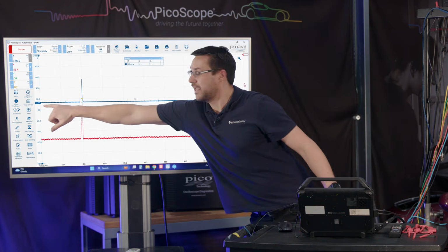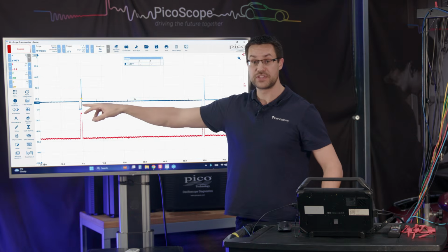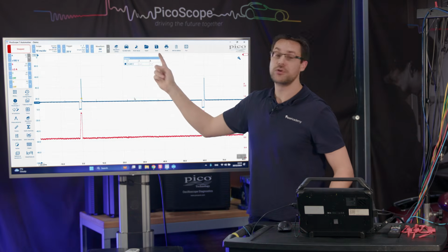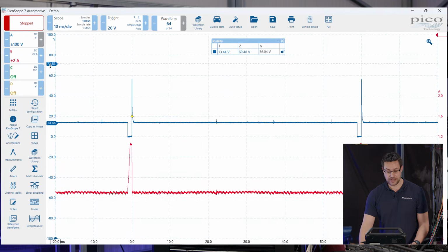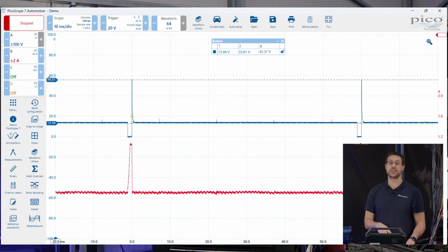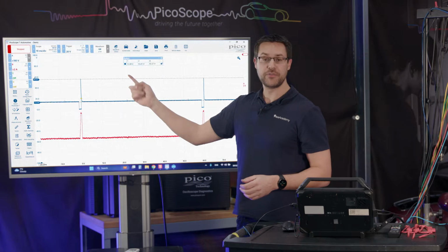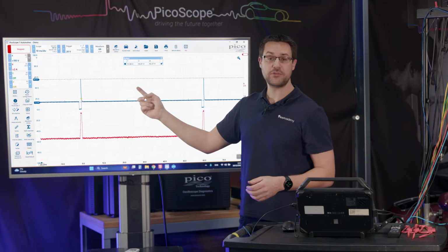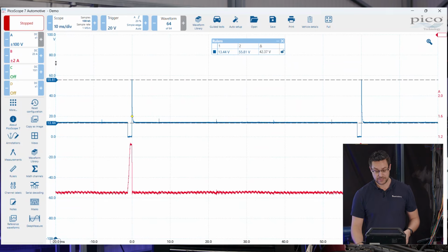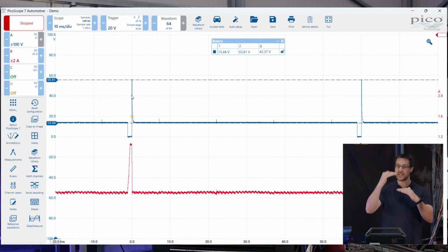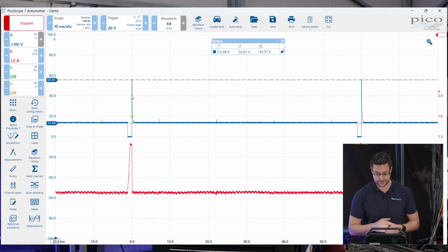You'll notice now that in the cursor it says a voltage value, or a value relative to that signal, and also we now have our ruler overview. If I was to drag another ruler, so there are two rulers for each active channel, we now have the value from the first ruler, the value from the second ruler, and the difference between them, so the delta value. Now that can be useful for when you're trying to analyse certain parts of a waveform to give you an idea about voltage levels.